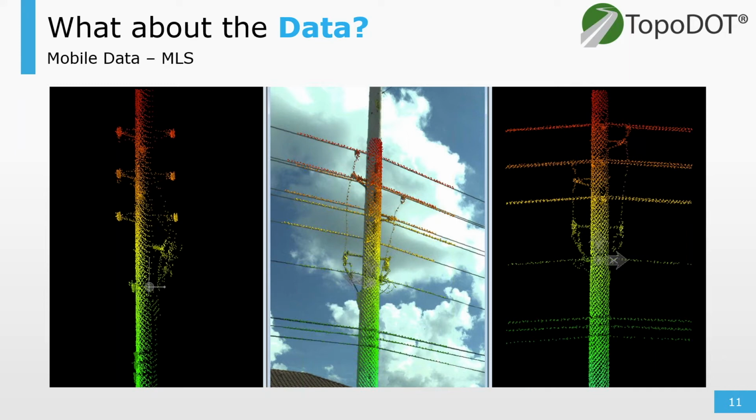And what we're seeing is there's two elevation views of a shared pole. It's colorized in elevation, including the system's high-res image in the center. And again, the imagery is important because this will be used to identify the finer features, tag number, pole material, condition, etc. If you actually look towards the top, you can see the number on the pole marked as 74. So the imagery is great, while the LiDAR data is going to be primarily used for positional and dimensional information.